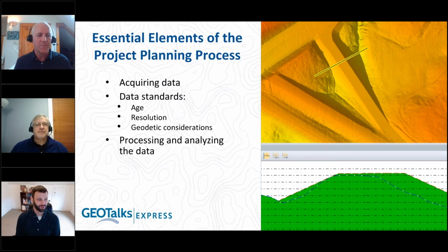So, I think it's important to understand what you need in terms of that if we're talking about geodetic accuracy, right? So in today's workflow, we may need to be really spot on, but if I'm just surveying a fire hydrant, do I need to know where it is down to the centimeter? Maybe not. Where is it appropriate? Definitely, absolutely. And obviously the appropriateness of that is very much relevant to the project at hand. So again, a little bit later, we'll actually show this idea of analysis of our data, and we'll go through some simulations to show how that would work.